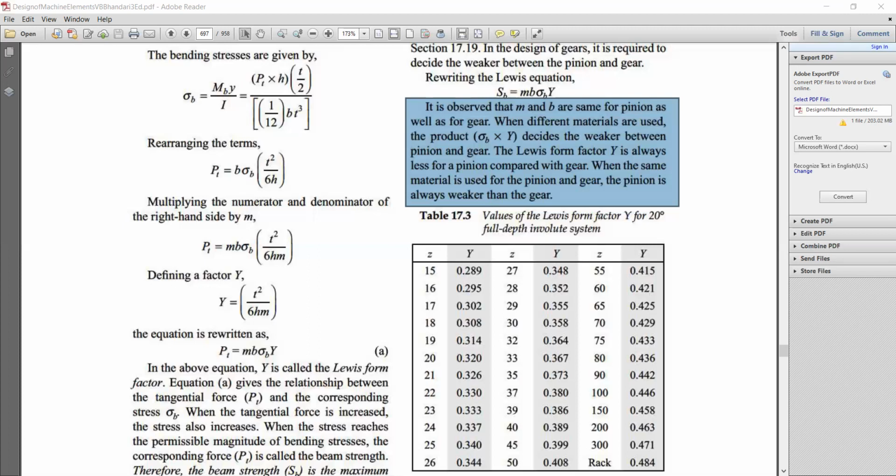Now refer to PSG page number 8.13, which is very important for us. So here, table number 8. Okay, you can refer to this table number 8 for design purposes. Because here you can look at equation 2.1. In 2.1 the equation is given: m is greater than or equal to 1.26 times the cube root of design torque divided by y, design sigma b, psi m into z.